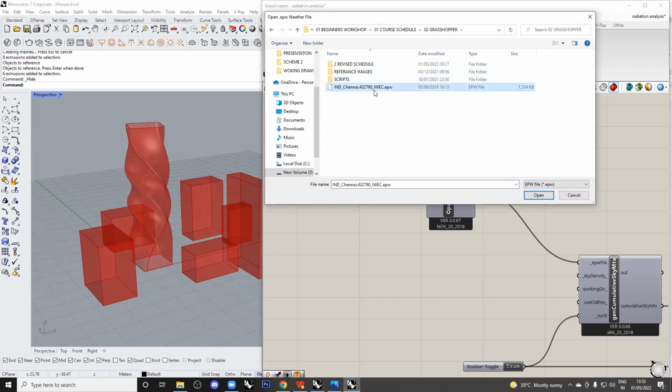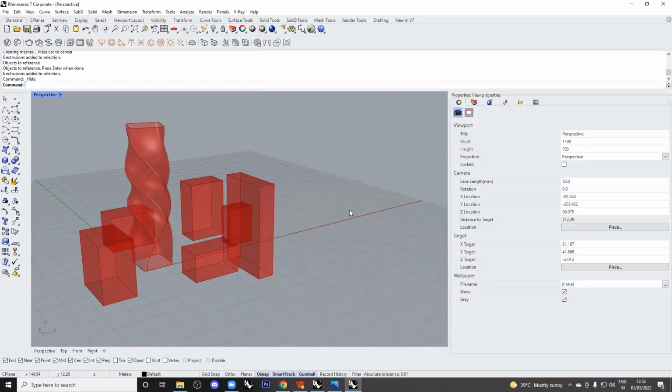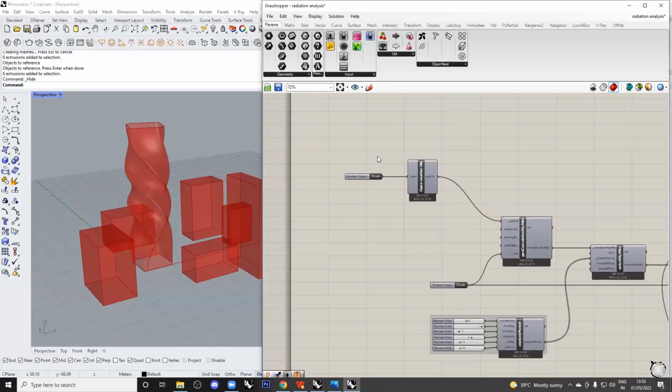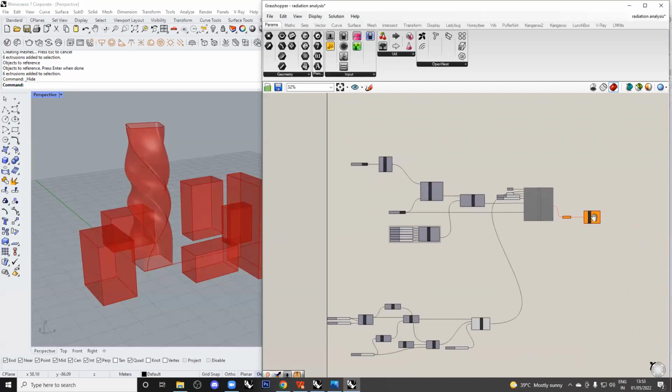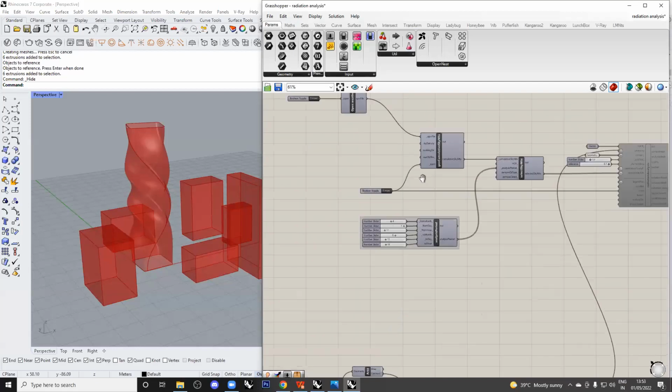Similarly, you need to have downloaded it for your city. Just select this file as soon as you open this document, and wait a few seconds. It is trying to process that EPW file, so the system will not respond for a bit. This is also the reason why I ask you to disable the main component as soon as you open the algorithm, because it will take time every time you change this input. So now the EPW file is also set.